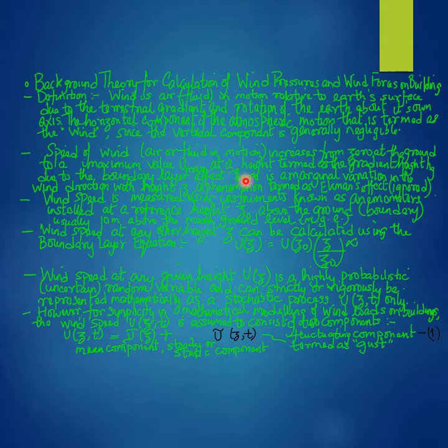Speed of the wind, that is air, essentially a fluid in motion, typically increases from zero at the ground, that can be considered as a boundary in a boundary layer flow, to a maximum value denoted as Umax, for example, at a height termed as the gradient height, generally denoted as H subscript small g, due to the boundary layer effect.